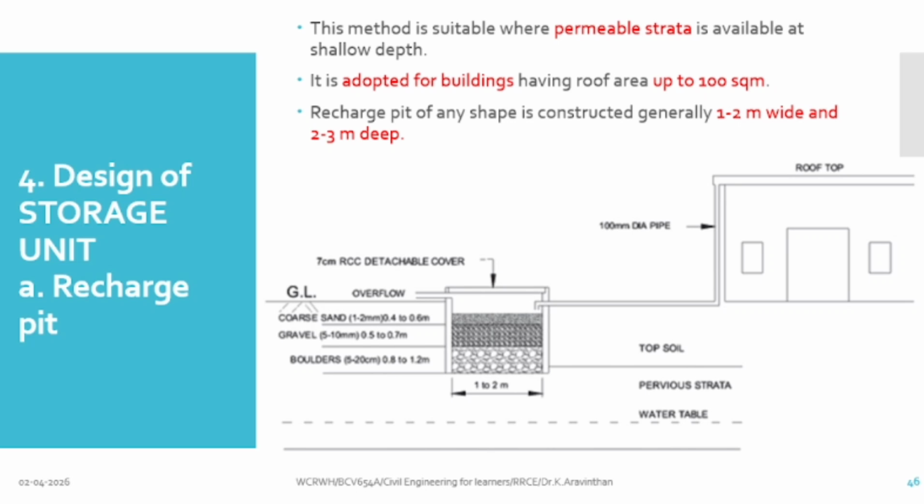If your roof area is up to 100 square meter, you can use a recharge pit. For our class, can we use a recharge pit? Less than 100, we can use a recharge pit. What is our class area? 72 square meter. So, it is adopted for buildings having up to 100 square meter.